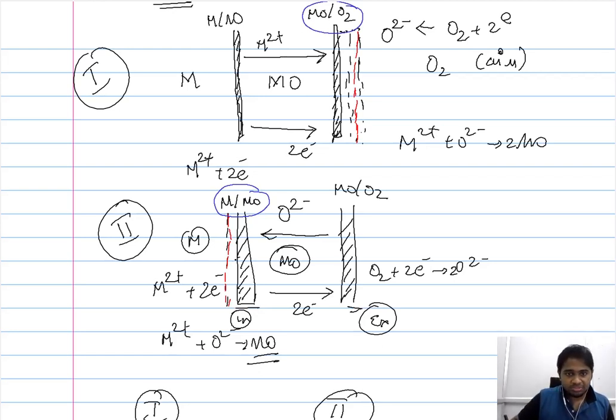Because in mechanism 2, it is the internal interface that is propagating in order to increase the metal oxide, and the oxide that you already have is more or less stable. When compared to mechanism 1, the oxides that form are usually newly formed and relatively unstable. In mechanism 2, the oxides at the external interface are more or less stable, so that ambiguity will not be observed. However, you have to take such considerations into account when the oxidation is occurring through mechanism 1. In mechanism 1, it is possible that the newly formed metal oxide might be removed and the thickness might appear constant, indicating that the consumption of metal has stopped. However, this is not usually the case.